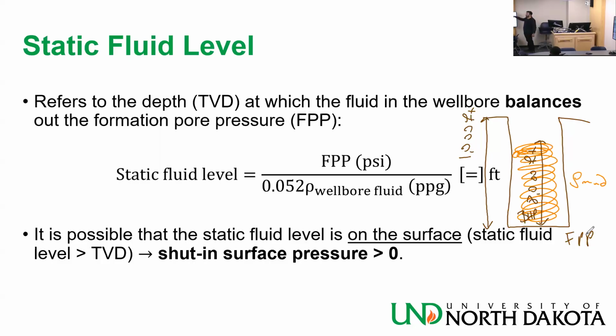I don't need the whole well filled with mud to balance this 4,000 psi, right? I only need 8,000 feet. So the static fluid level, I say, is at 2,000 feet from the surface. Yeah, and I put the comma wrong here. It's 10,000 feet, not 1,000 feet.